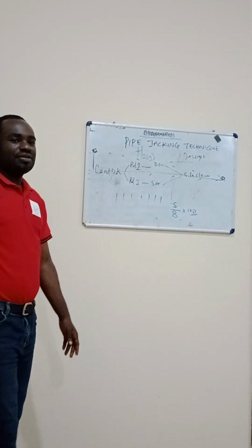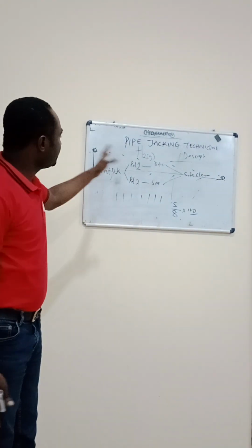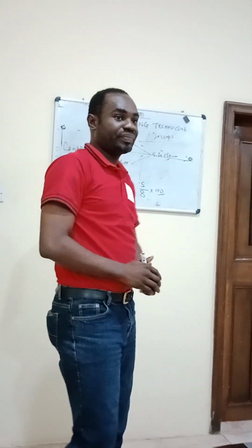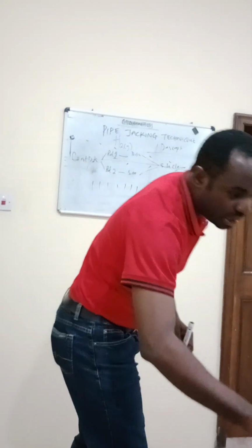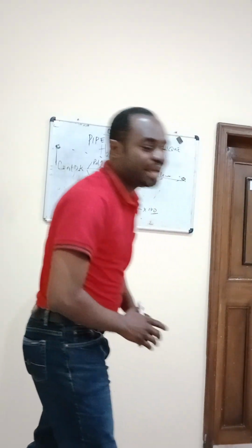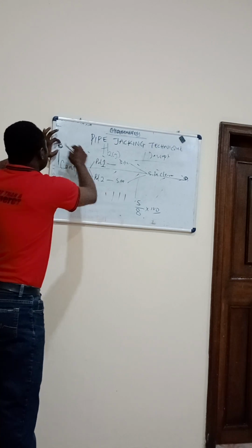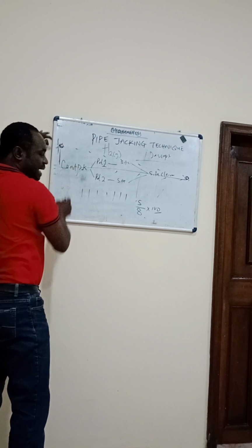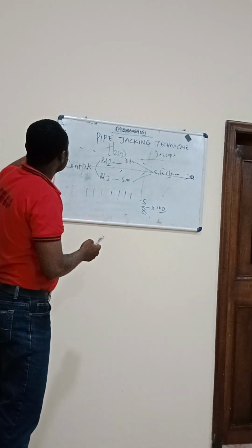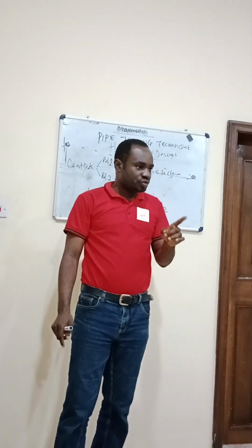But in this case, you don't need to do any physical surveys. You do it only once, and you transmit the data to the system, and then you can monitor the data from the system in one place. Besides, I will show you some pictures about this. Okay, so now you will use it to make sure that you maintain the slope. When you have gotten this slope, you need to set what we call the laser lights here, such that the laser light will carry that slope and will be beaming all throughout the time of the construction.